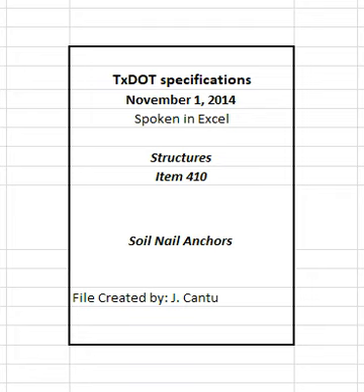Record the following information concerning the grouting. Type of mixer. Water-cement ratio. Types of additives. Type of cement. Volume of grout. 4.4 Soil nail anchor test.